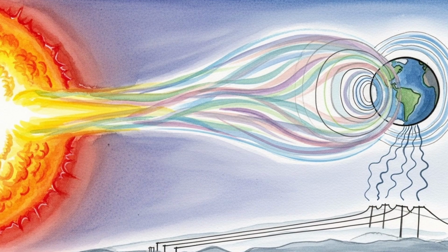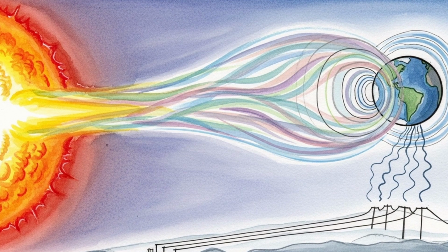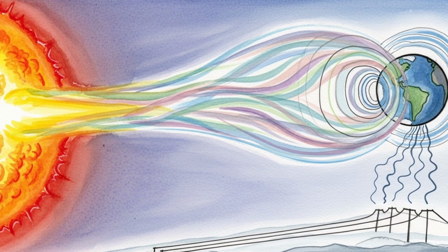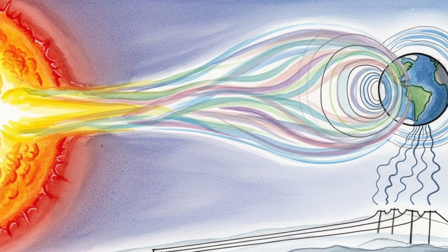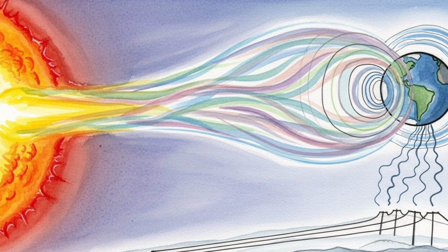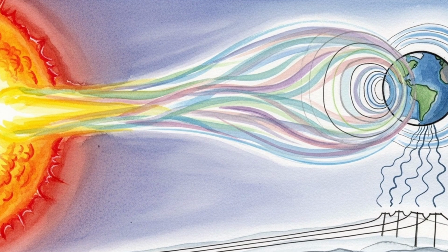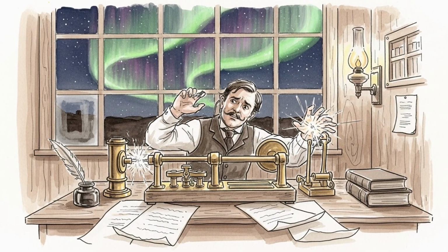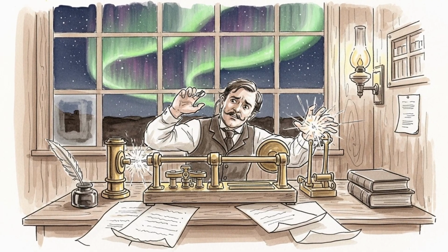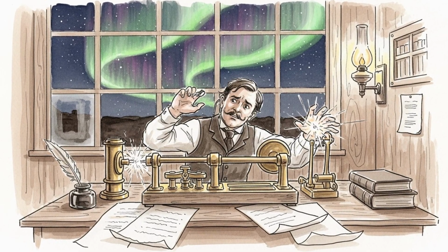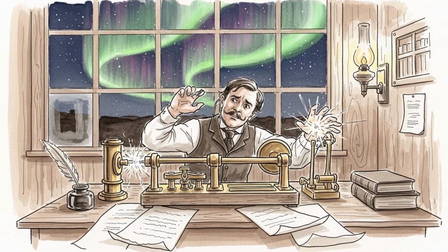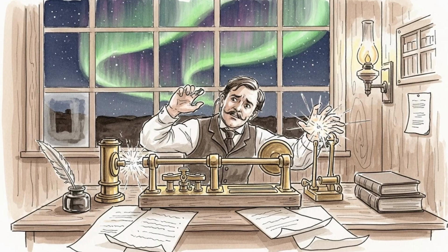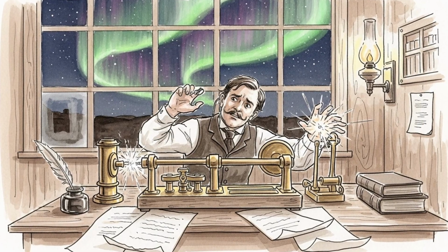Fast changes in the magnetic field at Earth's surface create electric fields in the ground. Long-grounded conductors pick up quasi-direct currents called geomagnetically induced currents. Power grid equipment is not designed for large direct currents. Even moderate levels can stress transformers and protection systems. Other long conductors, such as pipelines and some undersea cable power feed circuits, can also be affected.